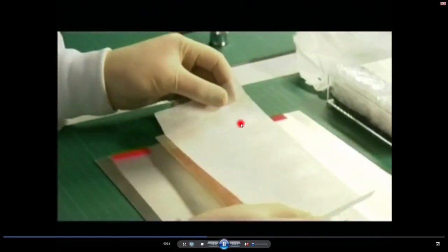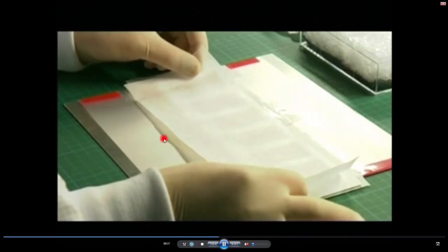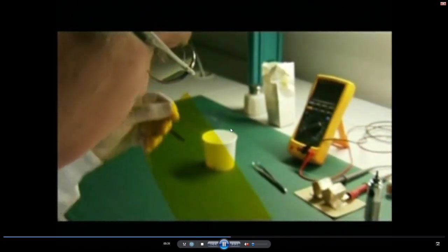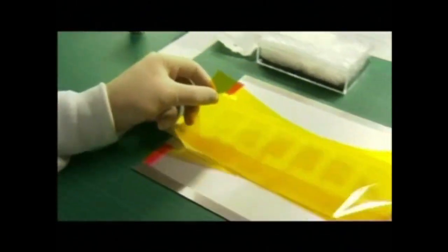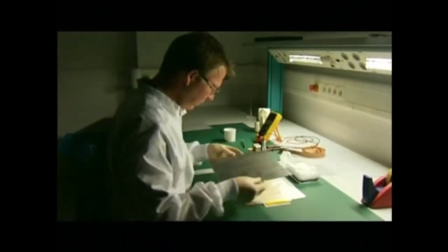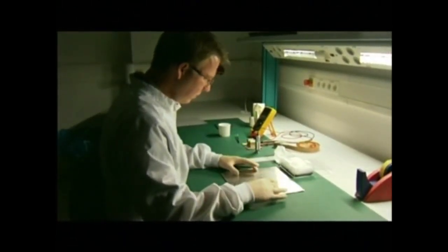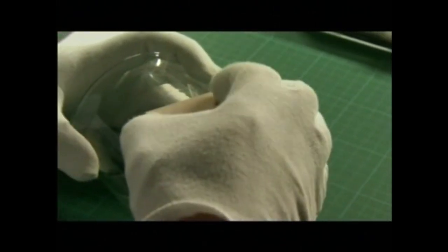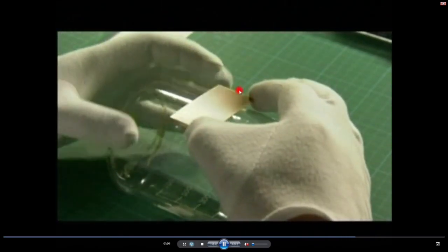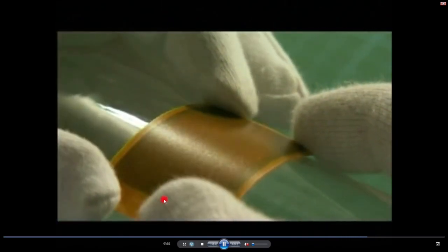Then the electrodes on the top together with the last non-woven ply, some release film, and then a steel plate so that you get really planar actuators. Before, the ceramic is really brittle, and after curing, you now have the flexibility to bend also the actuator.